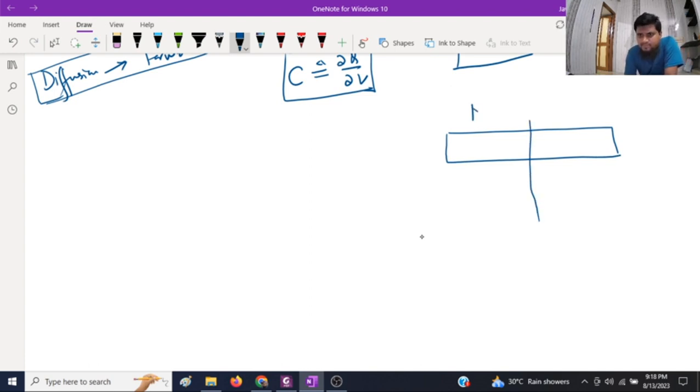Right. So let's assume this was the initial state where p-type doping was Na and n-type doping was Nd. If we plot the charge density, let's assume this was the junction area. So that will differ Xp and Xn with the value of Na and Nd.